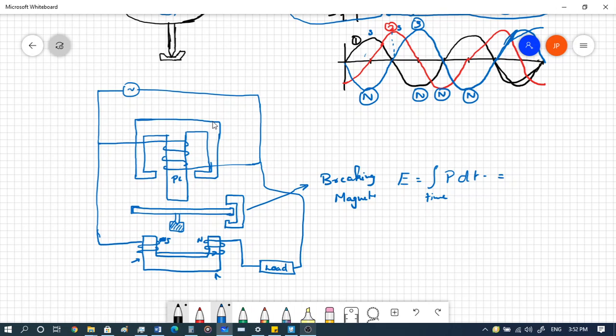So here we can see that the pressure coil, we have already told that 2 is the pressure coil. It is in 90-degree phase lag, right? 90 degrees phase lag. The reason is that we try to get a purely inductive coil, which can have a lag of 90 degrees.